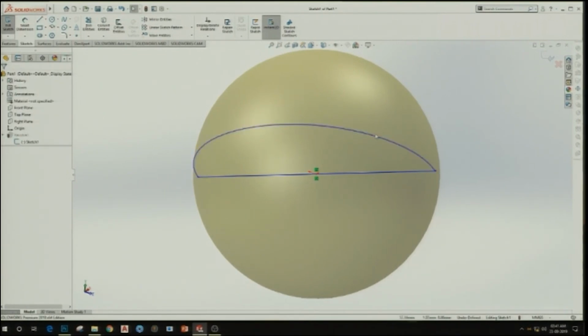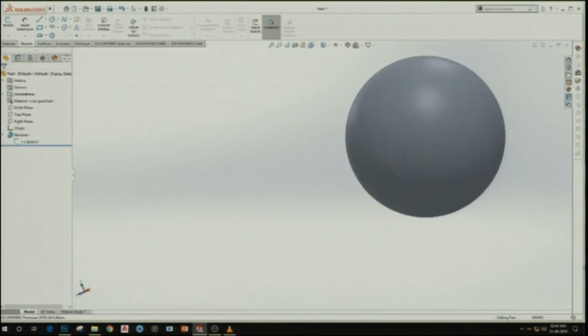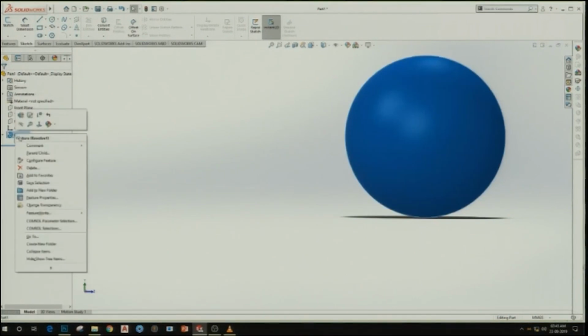So, it is basically a CAD software in which editing can be done very easily. We can change the dimensions, but it is important to note here that a change in dimension of one object or one part brings change to the dimensions of all the assemblies where this part is used, if it is used directly. It has to be done very carefully. One has to be mindful of what he or she is changing. So, let us try to see some other operations.